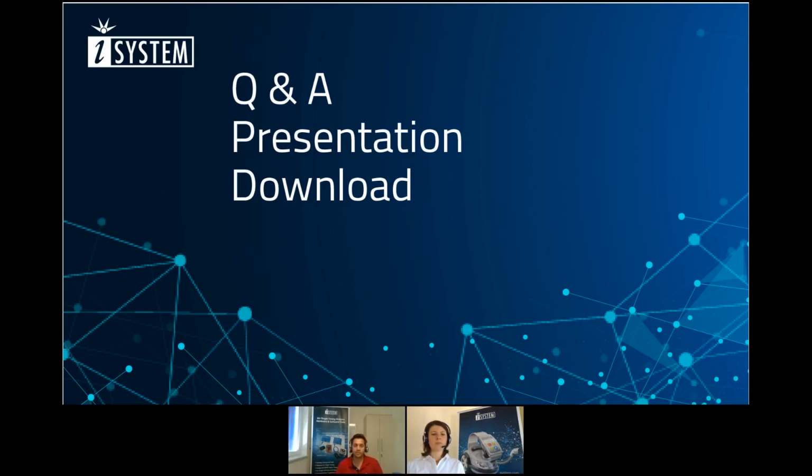It consists of a few shift instructions, and at the end there is a load instruction to the ITM stimulus port. So overall, I would say hardly 5 to 10 assembly instructions. So it's negligible, and definitely it's recommended.